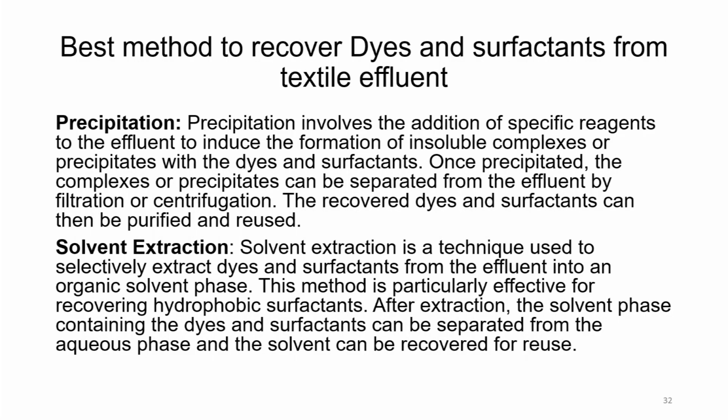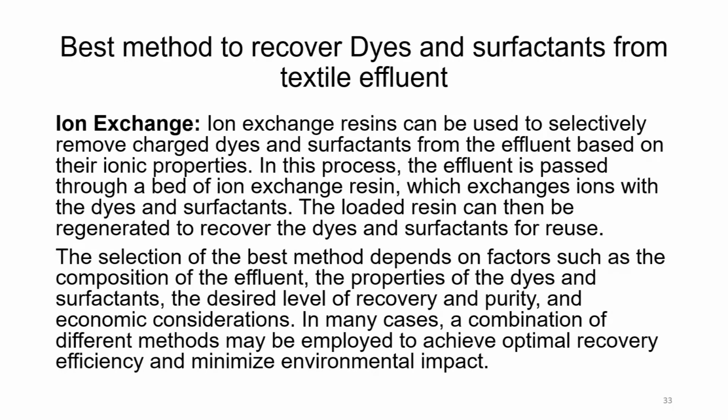Precipitation is also one of the methods which are categorized under best method. Solvent extraction is another very unique method which we did not discuss much in detail, used selectively to extract dyes and surfactants with the help of an organic solvent. After extraction, the solvent phase containing the dye and surfactant can be separated and the aqueous phase can be recovered from the solvent.